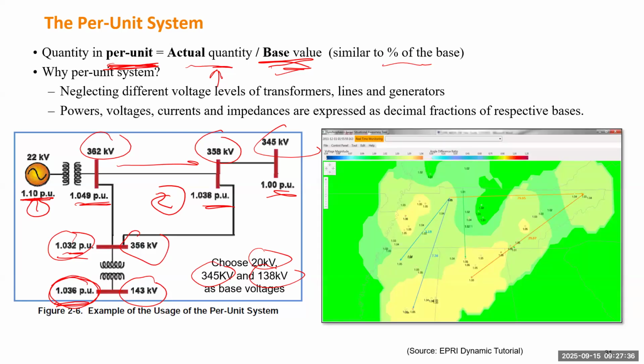Another example of this application is from a project I did back in 2010 for the Electric Power Research Institute. You may have recognized this is basically Tennessee. Yeah, this project was done for TVA. So in 2009 or 2010, we demonstrated one application which can collect phasors at many different locations of TVA substations. All the data is actually synchronized by GPS. Such equipment is called synchrophasors or phasor measurement units.